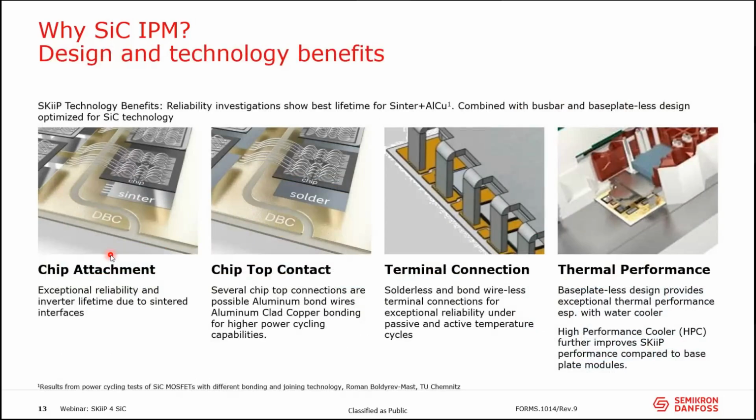Talking about technology benefits of SKiiP 4, we can start with the chip attachment. We have had sinter technology implemented in SKiiP 4 for 15 years already. It's something that we do, and it's a well-known process. And this has a very high impact on the lifetime of silicon carbide MOSFETs as well.